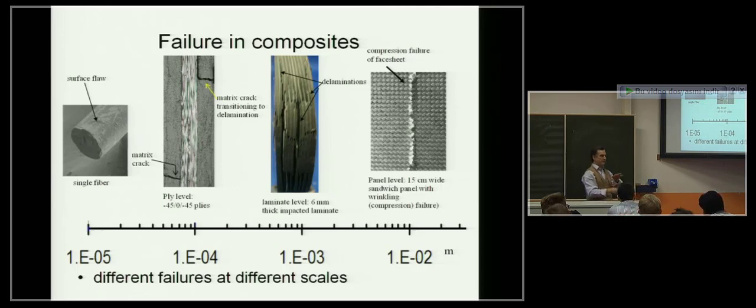Basically, as soon as a matrix crack reaches a layer or a ply with fibers in a completely different orientation to the fibers in the ply from which it was coming from, it now becomes extremely difficult to crack those fibers, and therefore you select to turn around. That means now the crack moves between the 2 layers and it becomes what's called a delamination.